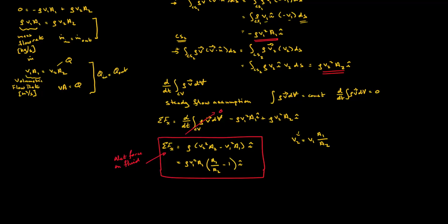We applied control volume analysis, and we separated the control volume into 3 control surfaces to show that the surface integral we used in our derivations of control volume theory can be expressed as a summation of integrals over the different surfaces defining the control volume.